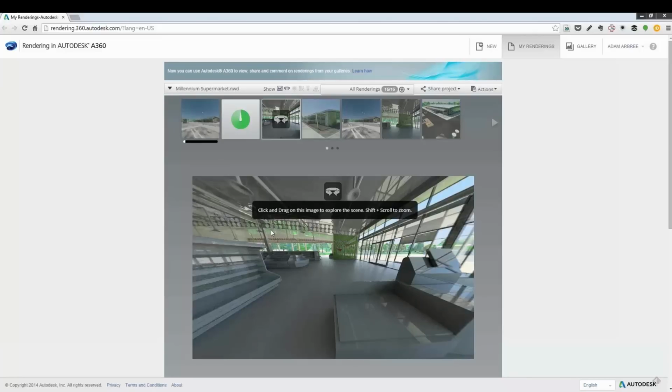Wayne asks, is it possible to utilize different rendering materials and different viewpoints in the same object, similar to changing the color per viewpoint? No, the rendering materials are actually set per model, so that would require probably setting up a copy of the model or something like that, and simply shifting the viewpoints across. So just save a copy as NWD and then apply different materials. That's probably the best way to do that.